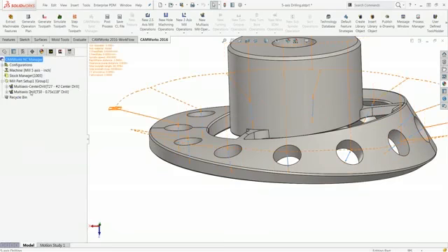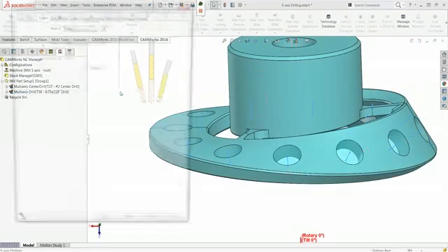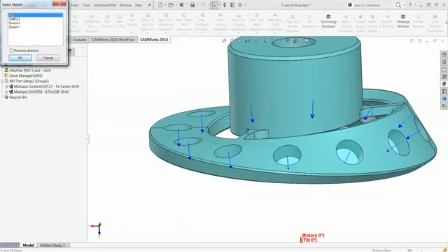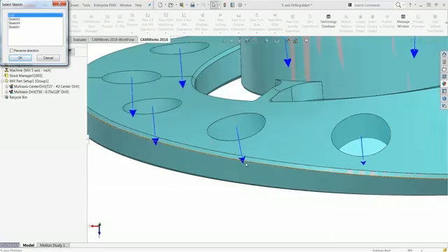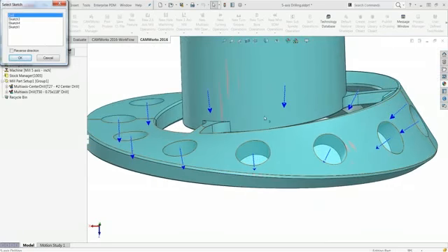So if I come back to my tool path, you'll see that our settings, when we select the line, so I'm just going to select that drill sketch that I created, you'll see that they actually put little tiny arrows on the bottoms of all of these lines. So I can reverse the direction. Maybe I want to come up from the bottom and drill those out. So that's definitely an option. It'll set them in one direction, but you can flip that direction.